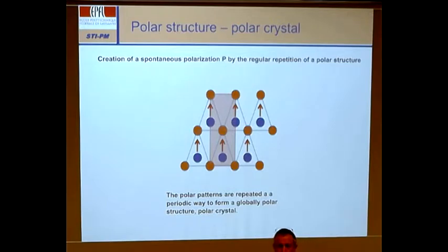Some people try to grow quartz that is oriented. Some French group managed to do that, but only little grains. To have all the grains in the right orientation is completely difficult. I think this will not be managed. It's very, very difficult. That's why we always stick to polar structures in thin films, because we have some means to grow not only oriented so that the z-axis is up, for instance, but also that plus c or minus c is oriented. This has to be done. In piezoelectrics, no problem because it switches with the electric field, but this is an issue of growth, how to do that.